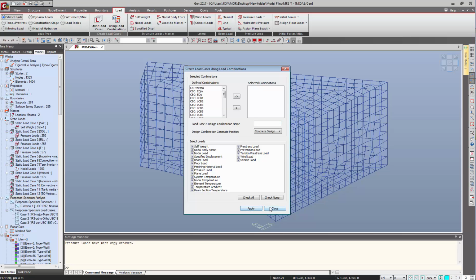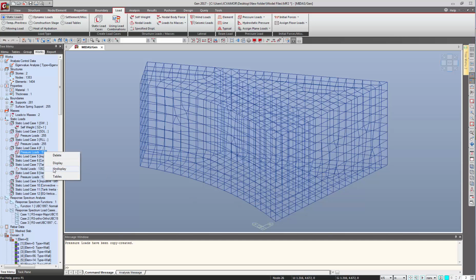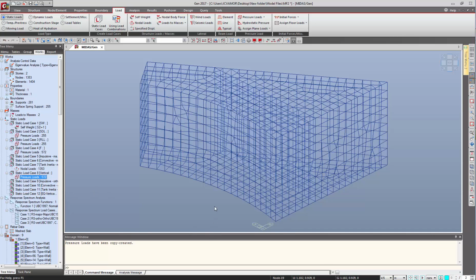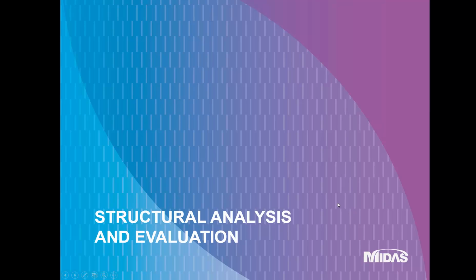After applying, now we can check this. So now we can see this is the hydrostatic load applied. When you increase it, we use converting to nodal load cases. So here's the magnified load. Instead of applying it again to the wall, we just use the easiest way, which is converting load combination to load case.